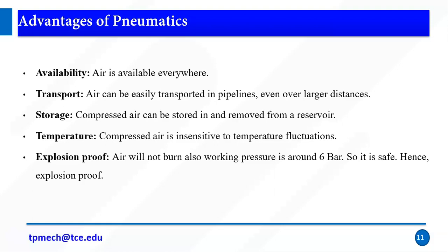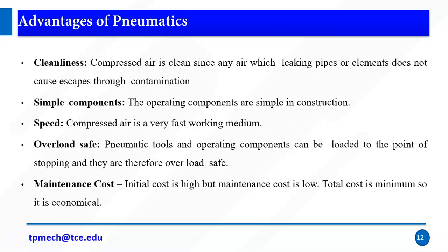Temperature: compressed air is insensitive to temperature fluctuations, so variations of temperature don't affect compressed air. Explosion proof: air will not burn generally. If an oxidizing content is there, then it will burn, but generally it won't. Working pressure is around 6 bar only, so very limited pressure, so it's safe, hence explosion proof, right? Cleanliness: compressed air is clean since any air leaking from pipes or elements does not cause contamination, so generally it has good cleanliness.